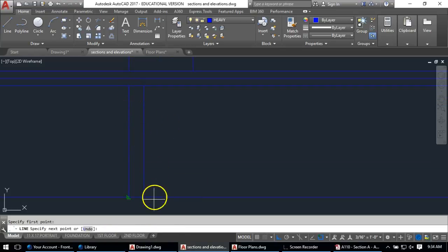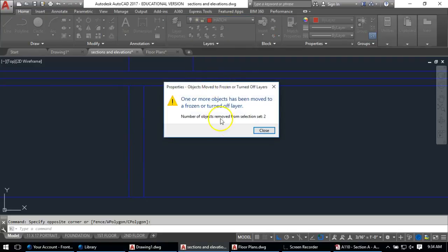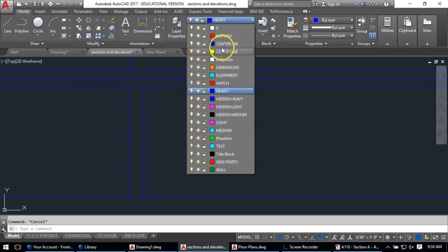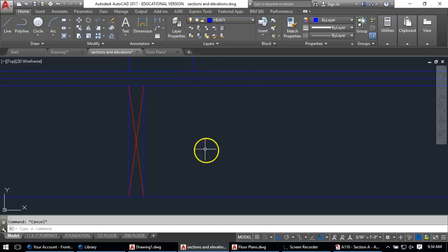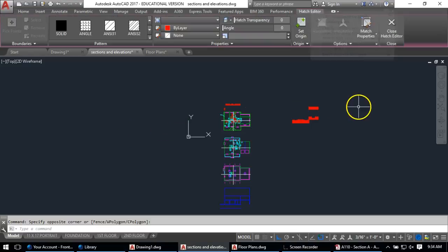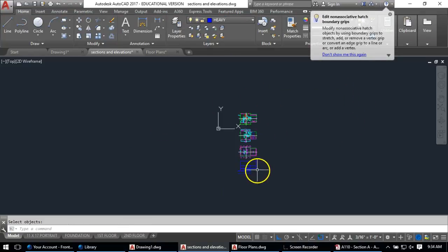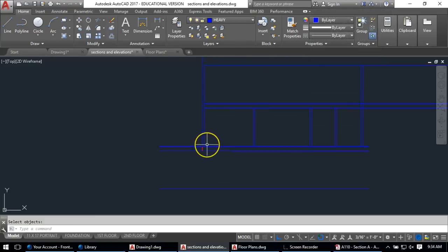I'm going to put an X in here because that's what we put when we draw lumber that we're cutting through. We put an X in it. I'm going to put that on the hatch layer. So I turn on my hatch layer. That means I forgot I turned it off and I just saved. I didn't copy, so I can erase this hatch layer. I was intending on copying them into a different file where it wouldn't have the hatch layers. I just turned them off.